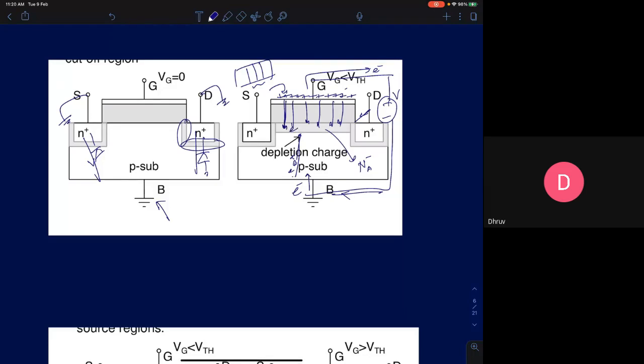But this is a p-type semiconductor, so there are already a lot of holes near the surface. This electron will first recombine with those holes. It's a trivalent impurity, for example, imagine a boron atom. Silicon has 4 valence electrons, and it forms 4 covalent bonds with its adjacent silicon atoms.